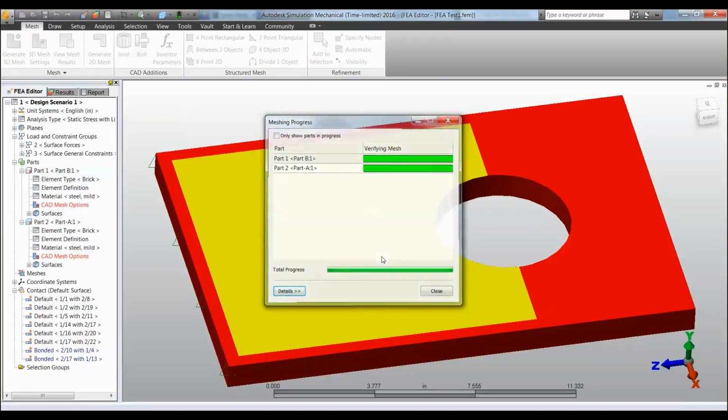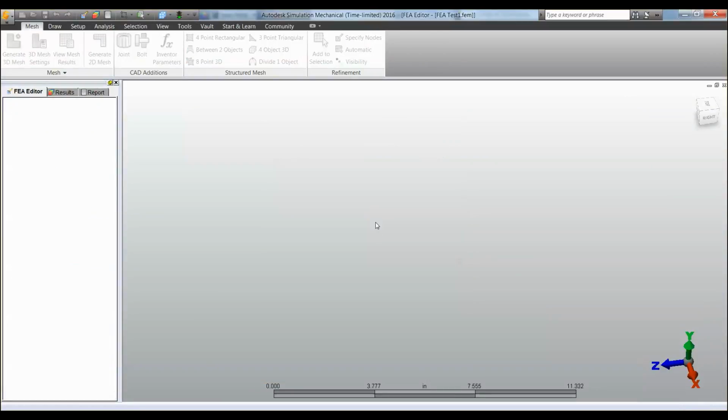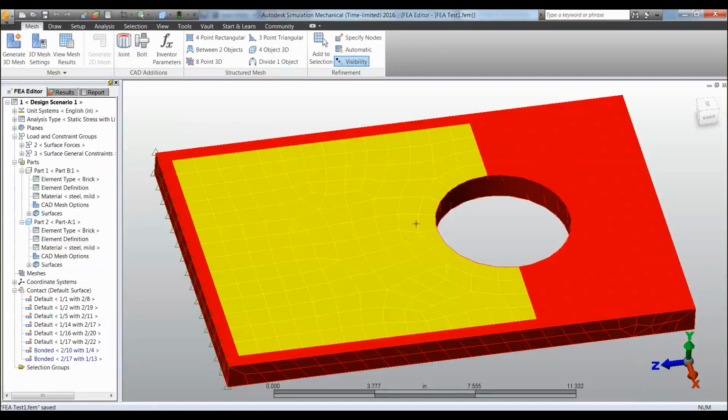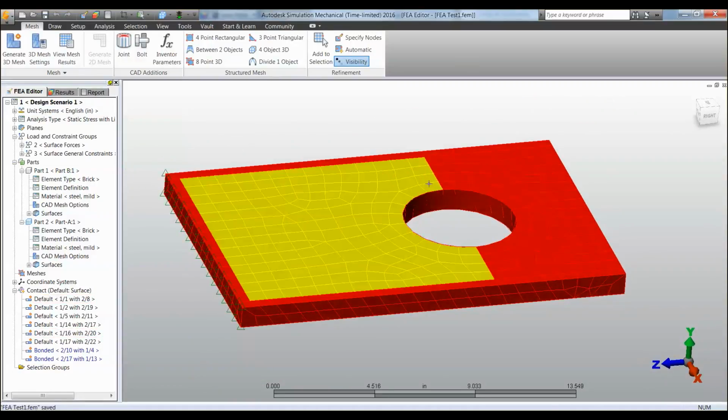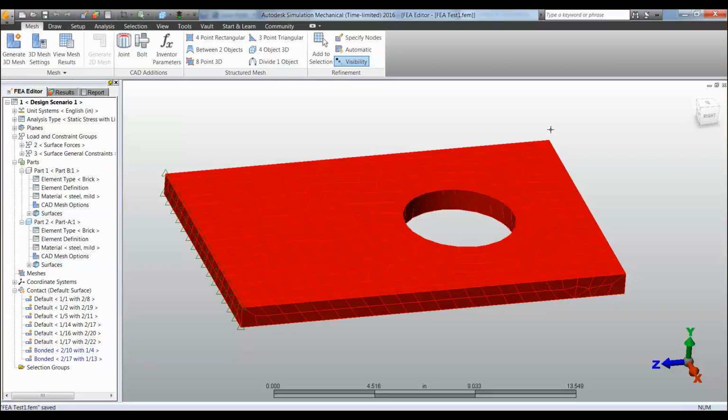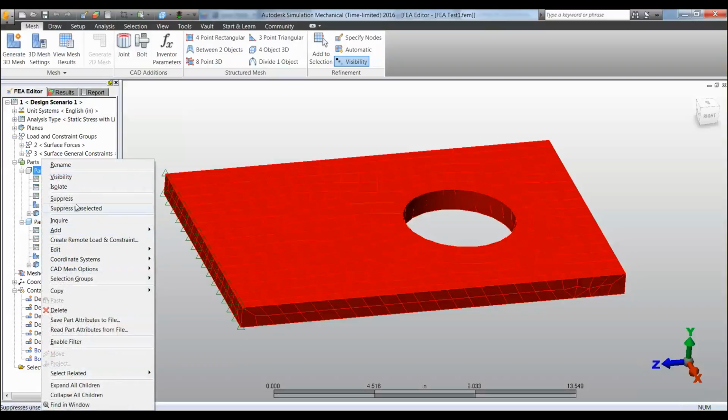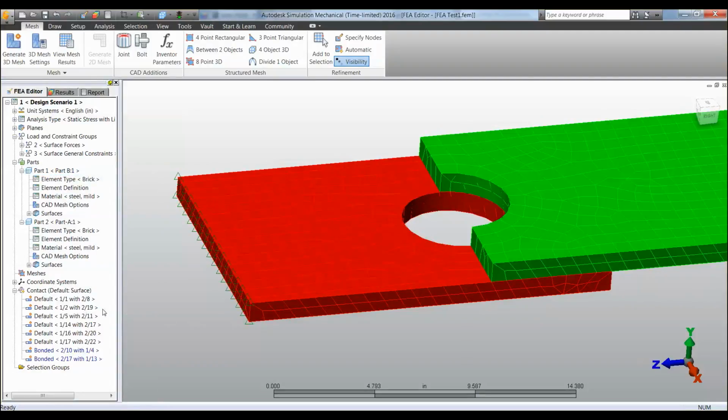Just going to bring this in, and left that one part off, you can kind of see now that it actually saw the surfaces that we're touching, and it automatically splits those faces. So you can see there's different selectable faces in here. Turn that one back on here. See it? But it also generated all the contact pairs so that I can actually see which ones are which.